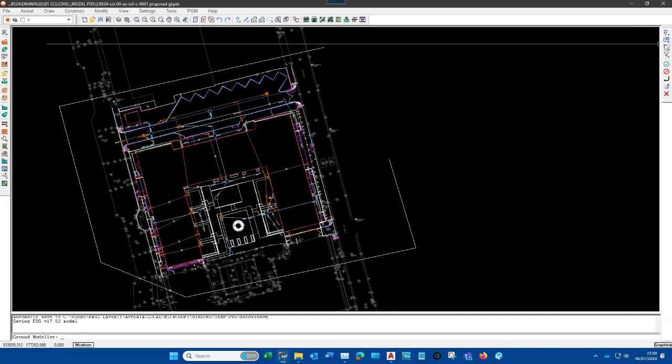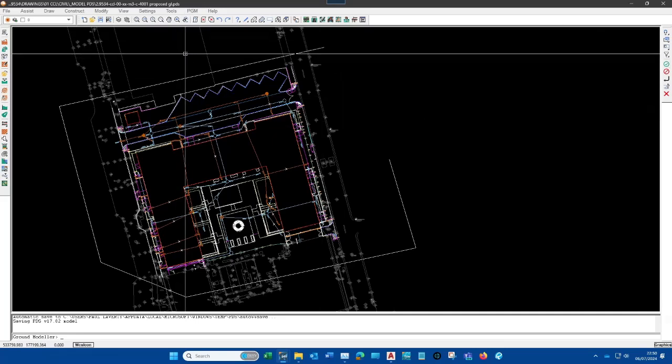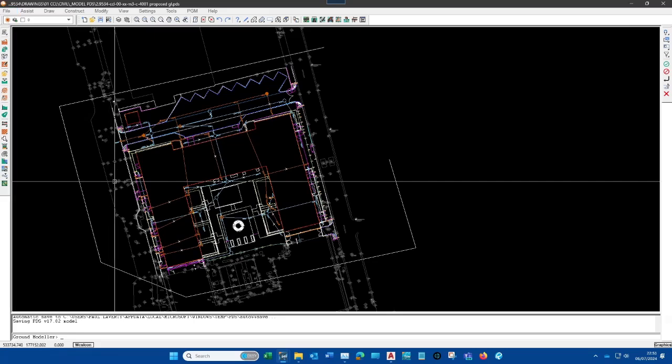This is your data retrieval toolbar. Basically, you're using it to choose the snaps, choosing the window to select objects, changing between digitize something or selected object for a command, cancel a command, among other things. And then here, this is what you're using to choose which module to go to, although you can do that by going into file and choosing the module there.